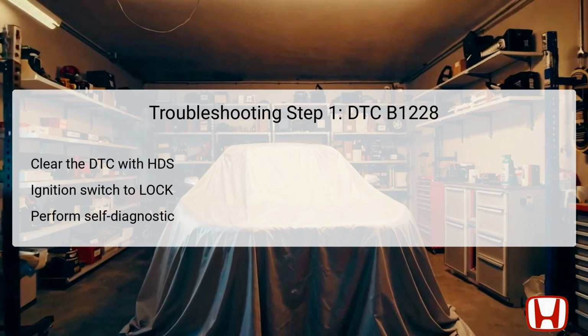After resetting, perform the self-diagnostic check utilizing the HDS or the climate control unit. Following the diagnostic process, check for any DTC indications. If the DTC B1228 is indicated, you should proceed to the next step in the troubleshooting process.